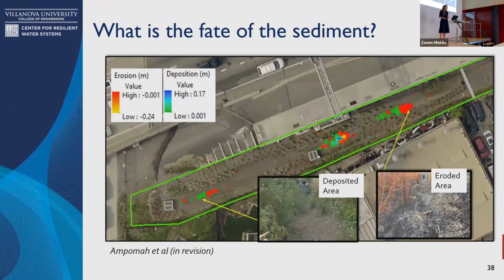And when we did, we could go out and look at areas and easily find areas of high deposition and high erosion. And so we realized by just changing the geometry of these systems, we can force the shear stress to change. And therefore, we're altering the hydraulics and forcing that sediment deposition to happen in different locations, right? So alter the hydraulics, change the shear stress, therefore alter your erosion and deposition patterns.